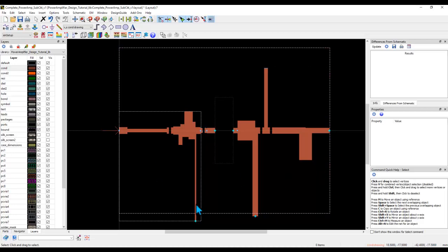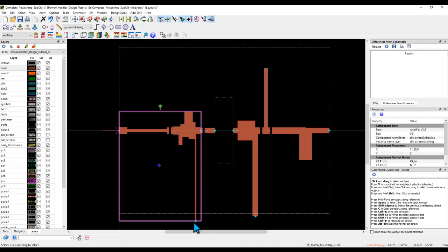But keeping a 100 micron offset is always helpful so that you still have some cutting tolerance when you cut this PCB. All right, so another thing which you notice, the bias lines for both drain and gate are going outside this board area, so that's not good. And also the way they are drawn, it's not the best utilization of the area available. So I would like to bend this line, I would like to adjust this line.